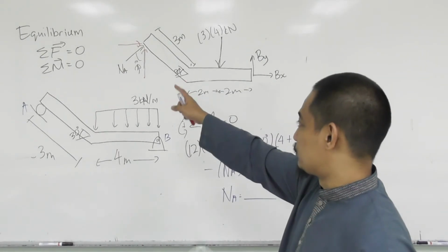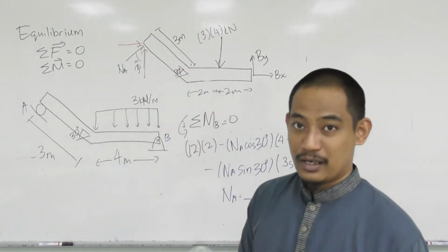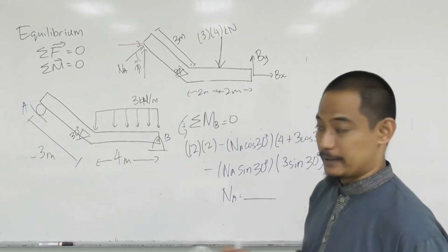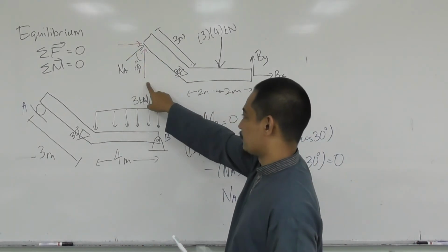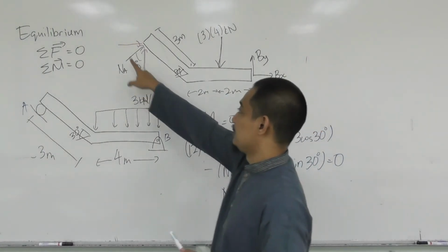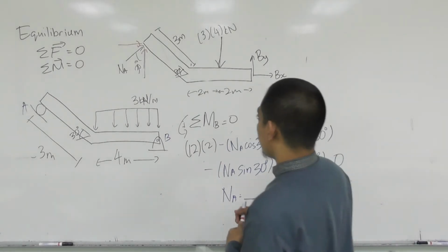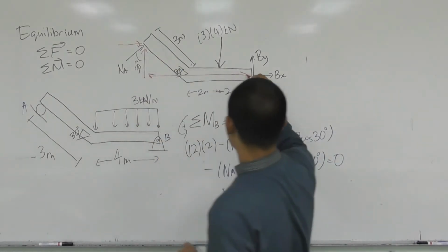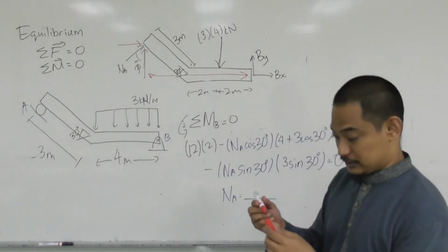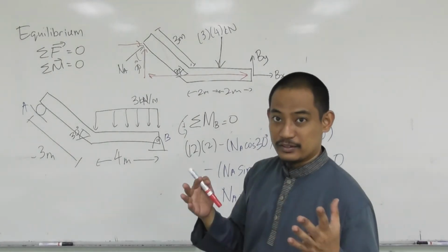What I'm going to show here is no longer a free body diagram, because I'm just illustrating how you calculate this. When you have this vertical and horizontal component, which are of course NA cos theta and NA sin theta based on this theta, or 30 degrees, this vertical one has this distance. When you draw, it becomes obvious. This is obviously the perpendicular distance.